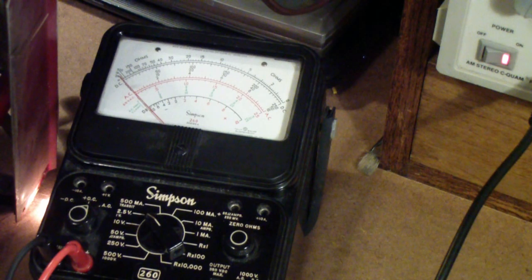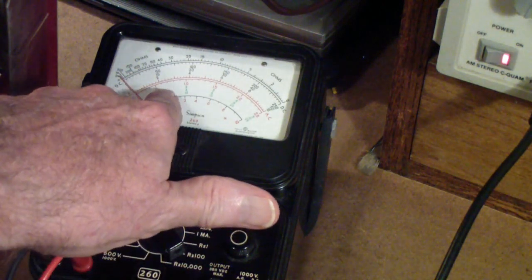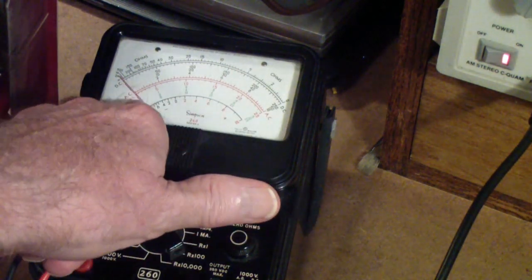Well, mainly because most people, myself included, find it difficult to peak a voltage using a digital multimeter because it's not continuously reading the value. It updates every so many fractions of a second. Some of them take a full second or 2 to update. So if you're using that, you have to adjust and wait, and adjust and wait, and hope that you're going to get somewhere close to the peak. Whereas with an old school multimeter like this that has an actual meter in it,